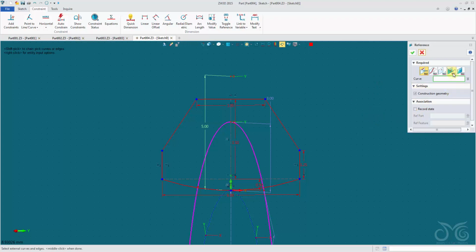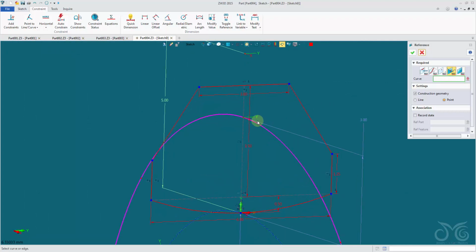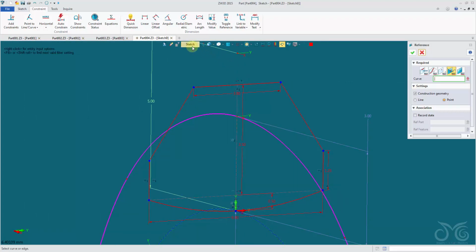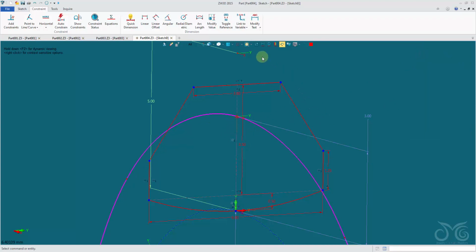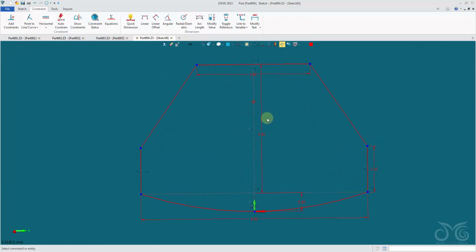Okay, we use the fourth referencing option, our curve intersection. We pick the curve, the outer curve. If you can't pick it, come into the entity filter, select curve, pick the curve, and it throws in a little red triangle at the intersection point. Now we can show target.